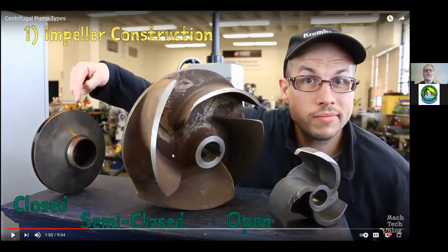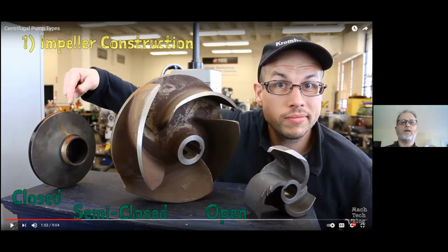So there may be questions on the exam about the 3 styles of impeller. So we're not talking about propellers, all styles of impeller. And mostly what we're talking about is the desired energy we want to create, and also the type of fluid that is passing through the impeller. The dirtier or the more mixed the fluid, then the more open the impeller. So we typically reserve the closed impeller for distribution systems, and you'll see the semi-open or semi-closed and open styles for wastewater or on the raw side of treatment plants.